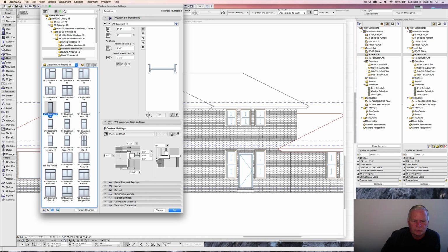4.5 for the standard window. Probably 4 9/16 is a standard. 4.5 is probably fine again, for our purposes. Here, as we look at it, the only one we might change, the sash width is 1 3/4. 1/4 inch is just this margin of rabbet that's right there, and this is the thickness of the glass at 1/4 inch.